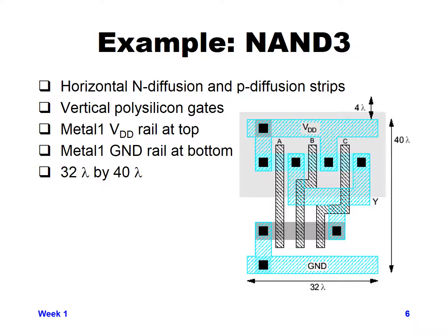So in this particular case, you need 3 polysilicon. You need the distance on each side of those polysilicon for 4 contacts to the P diffusion underneath. Then you need distance of the well that has to overlap that full PMOS or P plus region for the PMOS transistors.